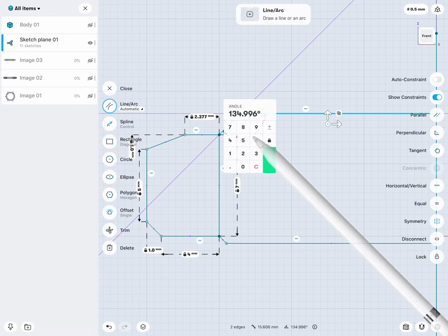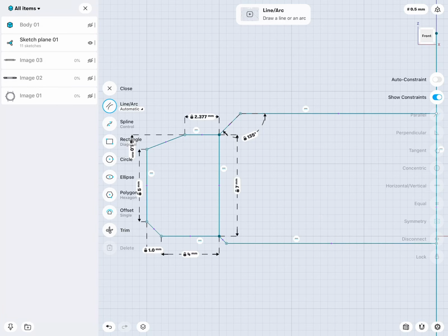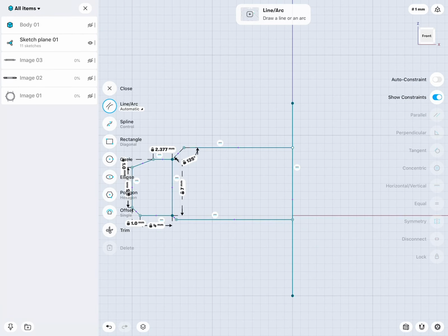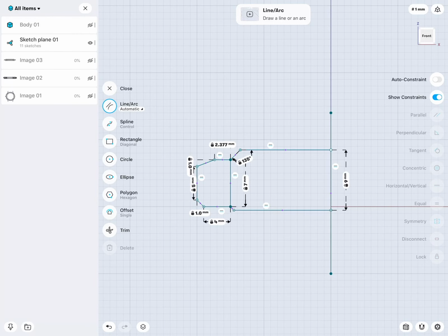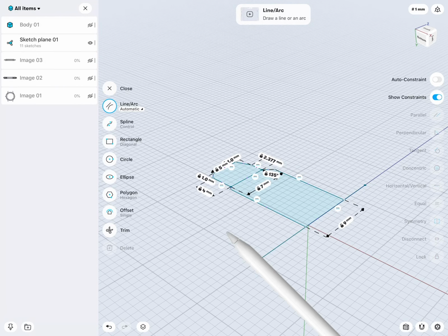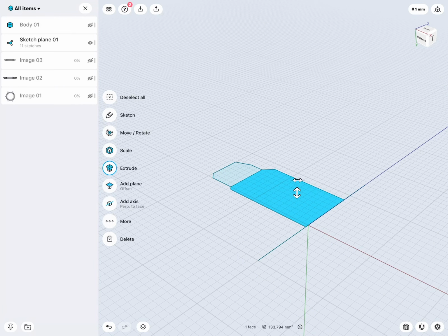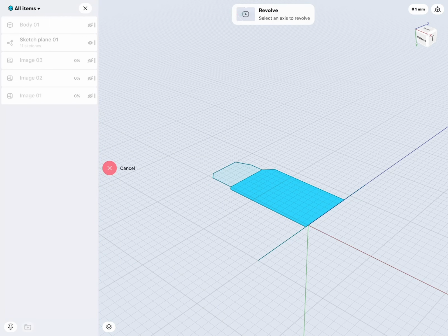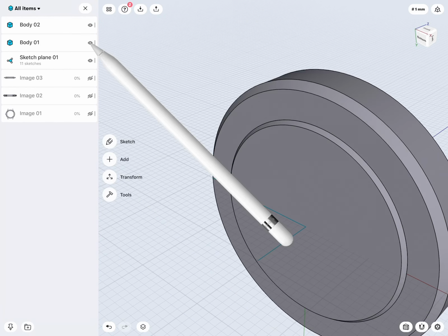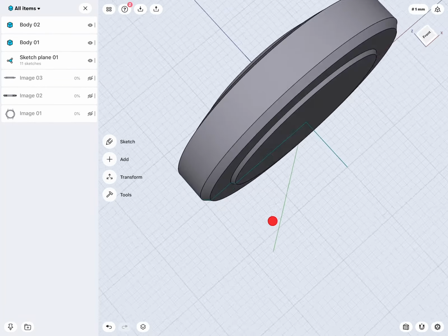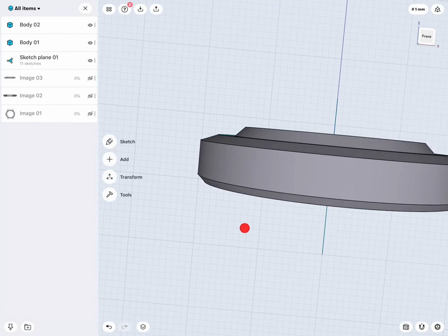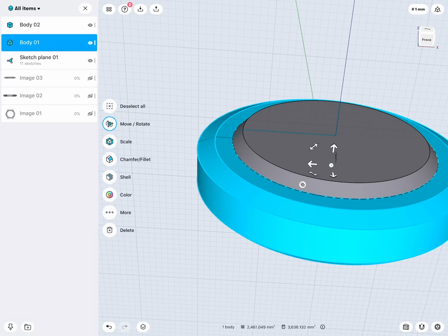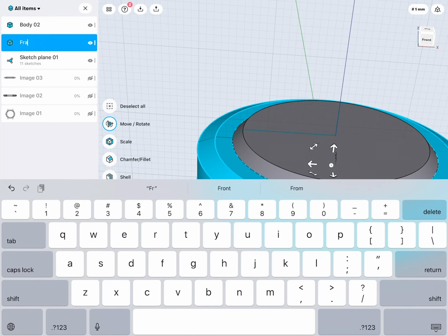This angle should be 135. Very good. There. And what is the height? We can specify this to 9 millimeters. Nice. Okay. Now we do one more rotation, and we do the same. Now we select this fill, go to more and revolve, select this axis again. Then we can show both objects, and there we have now the inside part and the bottom part, and then the frame and the outside. It also really helps when we give things logical names.